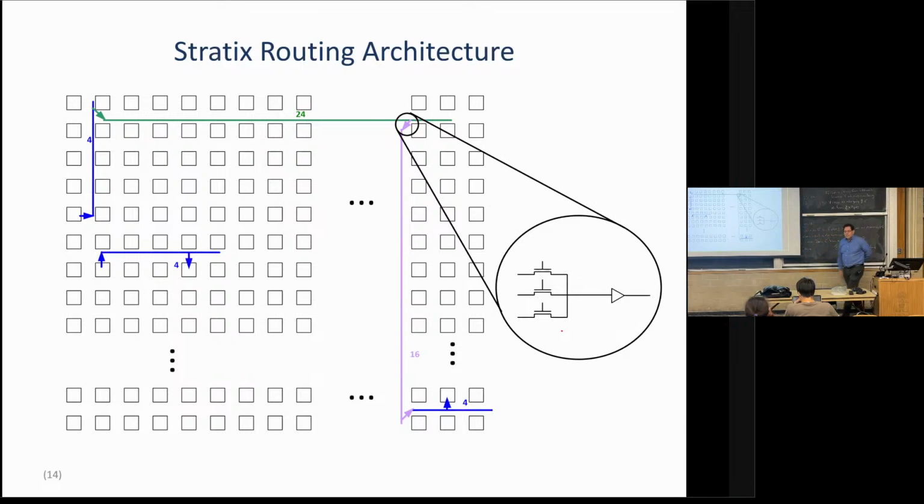Yeah? Does that necessitate the introduction of length 0 wires so that you can get directly onto a long wire without artificially going to the left and then back to the right? Okay, so the question, so Isidore was asking, do you need length 0 wires, which are essentially just muxes that, you have a mux that doesn't really go anywhere. Its output just connects into other muxes. Sometimes those are called length 0 wires in some routing architectures.